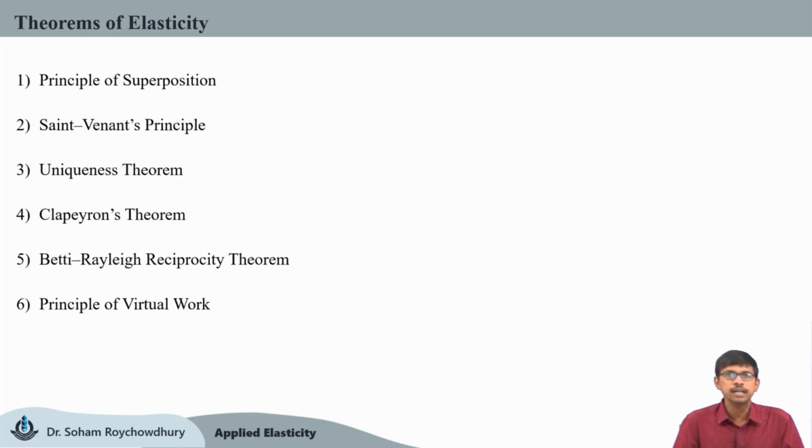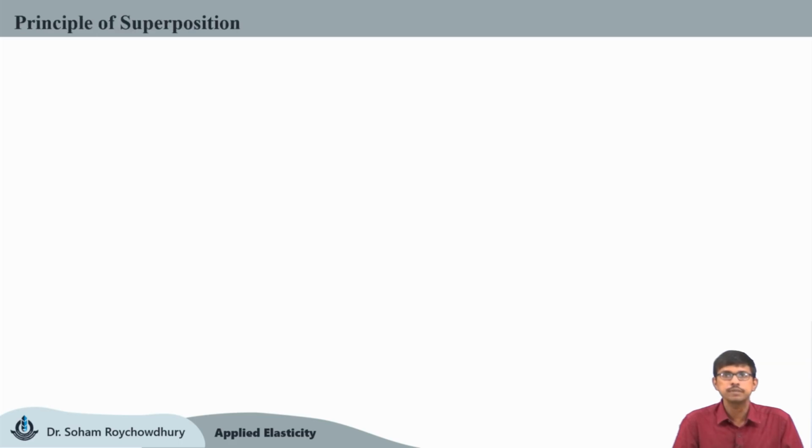So, first let us start with the first one, that is the principle of superposition. Now, this is valid only for small deformation problems and linear elastic solid materials, which are already our assumptions for the infinitesimally small theory of elasticity. So, these assumptions are also the same for the principle of superposition for elasticity.